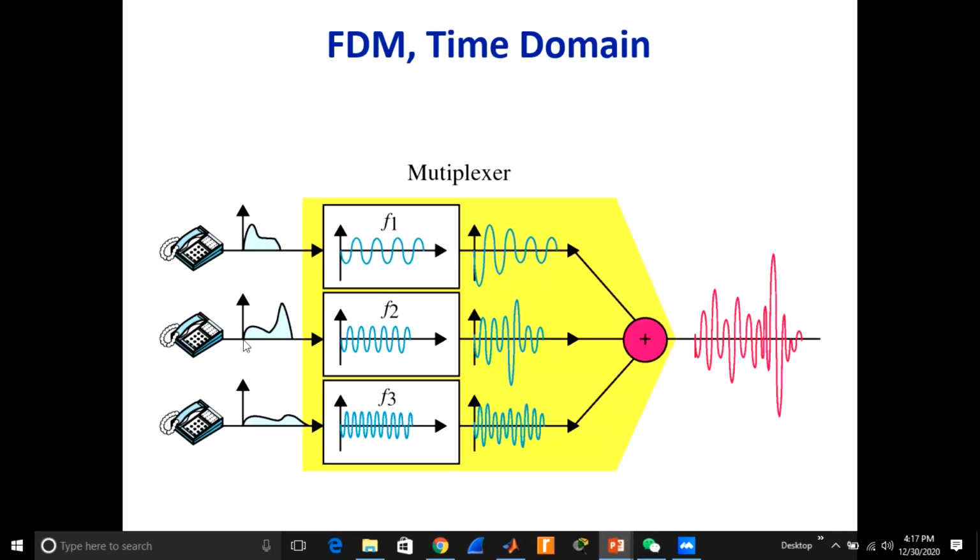And when we modulate this signal to this, it will look like this. Then we combine them by using an adder. So this is the combined signal. Now this combined signal is the sum of these three signals, so this is called a composite signal. The signal which is formed by the adding of some signals is called a composite signal. And these are called modulating frequencies.